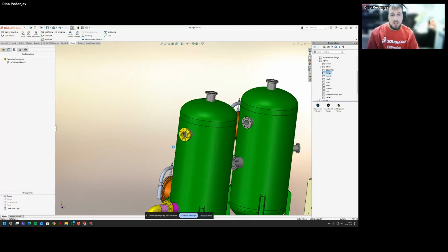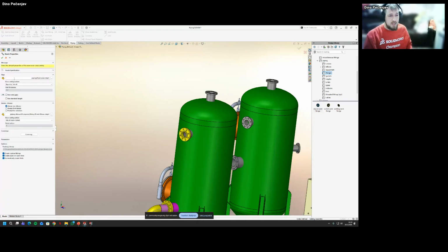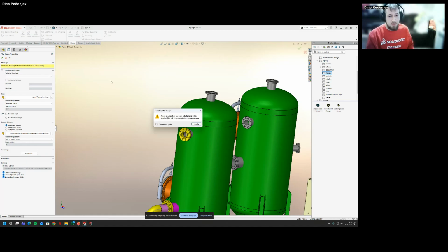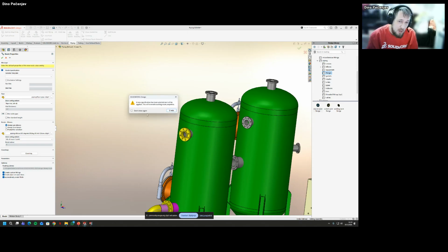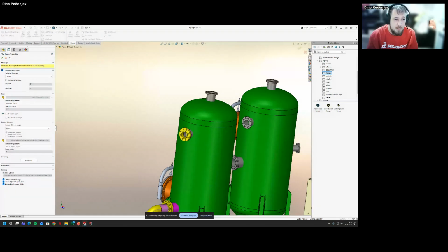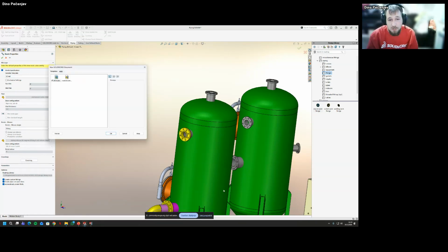Let's say we're going with this one, and it will automatically set the sizes. Here we are using route specification. If we modify any option regarding this, it will prompt us that everything will be overwritten because it will use the route specification template. With this, I'm set. I can start the route. I will select my template.